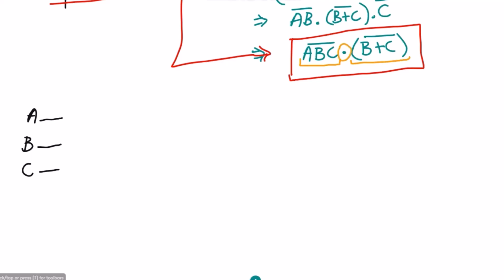So here first of all, in order to implement this circuit, I have to use the NAND gate. Okay, so NAND gate is here, and here the 3 input NAND gate should be used. So this first, this second, while this third, and here we will get A, B, C whole complement.